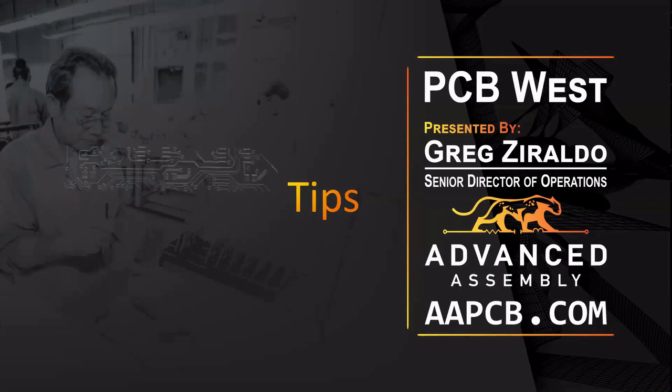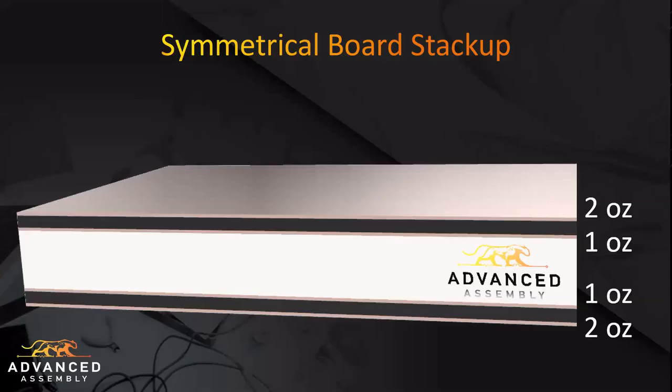So I want to kind of go over a couple of things you guys want to keep in mind. So generally you want your layer stack to be symmetrical. So on a 4-layer board, if layer 1 is 2 ounce and layer 2 is 1 ounce, then layer 3 should be 1 ounce and layer 4 should be 2 ounce. This is really going to create a board with greater stability.